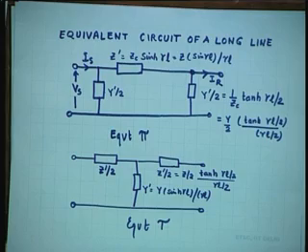The equivalent circuit of a long line we had derived last time, if you recall. We did an exact analysis of the long line, and we proved the ABCD constants in terms of hyperbolic sine and cosine. Then we gave two alternate ways of computing ABCD constants, and those formulas can be used. However, some people still want an equivalent T circuit, an equivalent pi circuit even for a long line. This can be derived, but I thought since all of you have already done it,